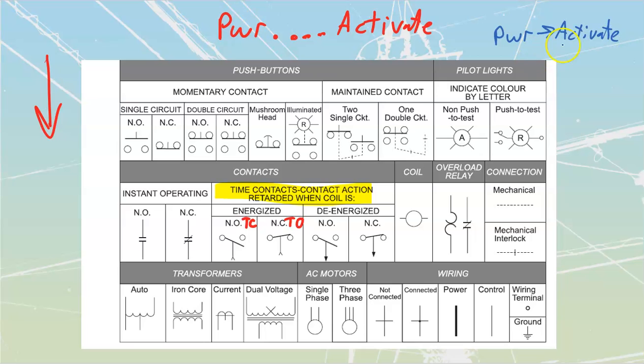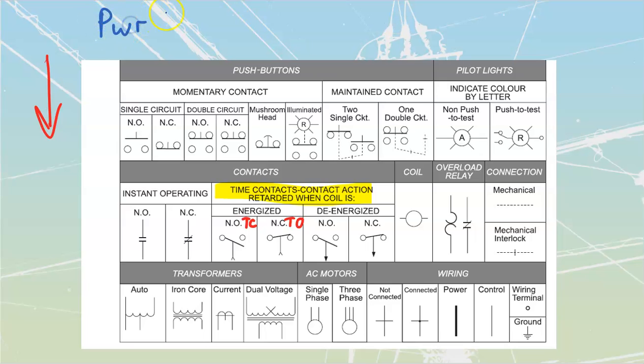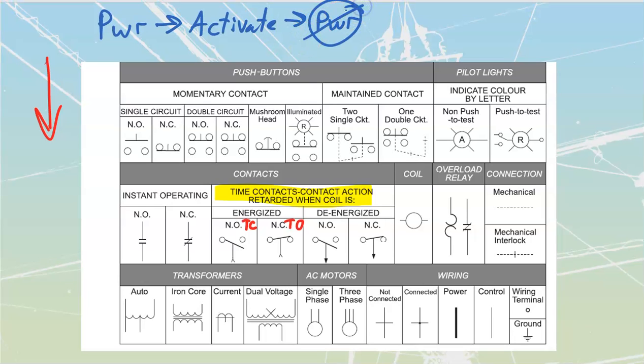And then when we depower them, they're going to time to rest. So they're basically timed to rest. I'm actually going to remove that whole top part because that's going to make it too confusing. Let me just lay out the contact points. So power, they instantly activate. Then they're going to stay activated. And then when we have no power, they are going to start their timing. Tick, tick, tick. And then they are going to go back to rest.